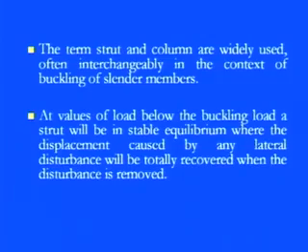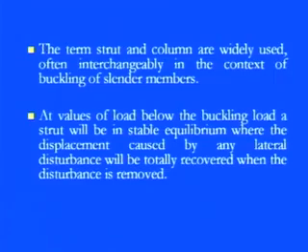So, as I told you in the very first slide, buckling is the key phenomenon through which we can distinguish that this slender member comes under the column, and this slender member comes under the strut. At values of load below the buckling load, a strut will be in stable equilibrium, where the displacement caused by any lateral disturbance will be totally recovered when the disturbance is removed.